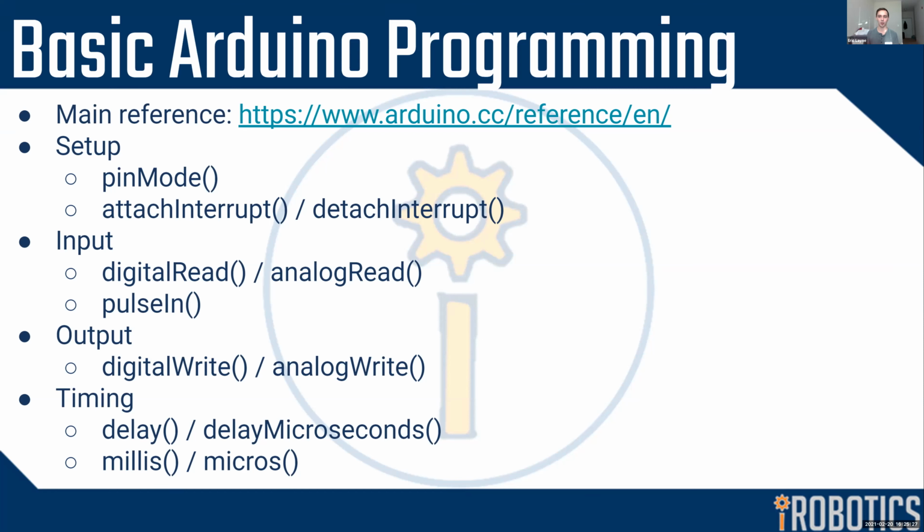You can make it happen a bit slower, because you may want to be reading in this digital signal as fast as you can, but you really only need to send data over your serial connection at a couple characters per second, maybe. So you want to control how fast each of those things run, rather than saying everything is going to run as fast as it can no matter what, because you waste a lot of resources and time when you do that with Arduinos, because they're very low power and low CPU power.